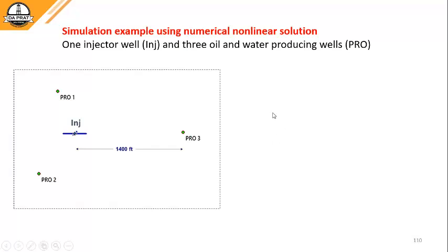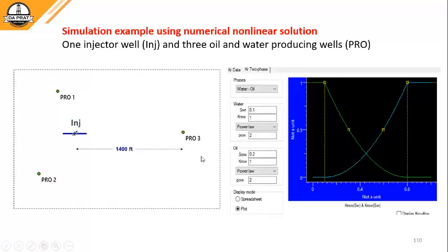Okay, let's present a basic example using the numerical simulator, and this is the case of an injector and 3 producing wells. This injector I intentionally fractured, just to make you aware that in field cases most of the injectors end up being fractured, and we're going to start injecting. I'll show you in the next slide the injection period and to carry out some fall-off tests.